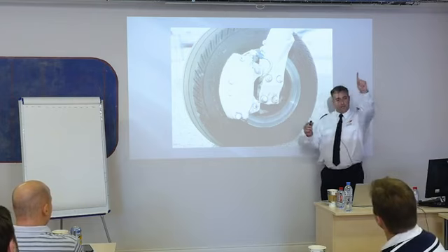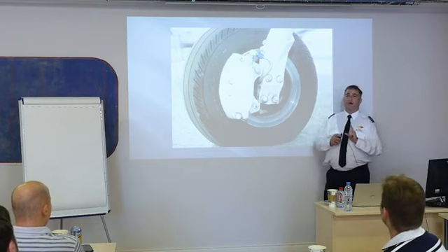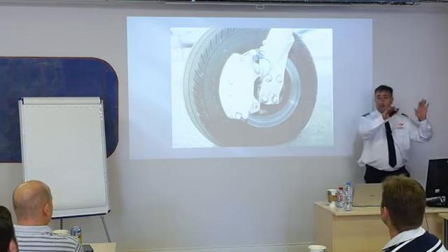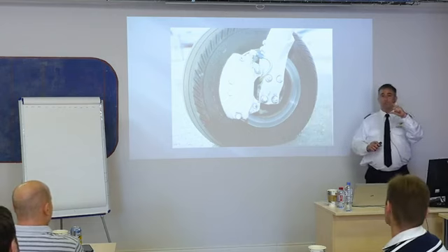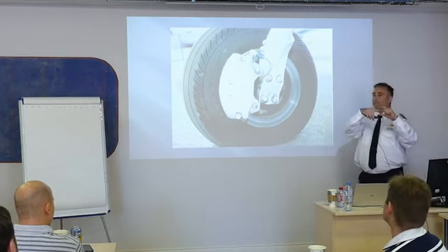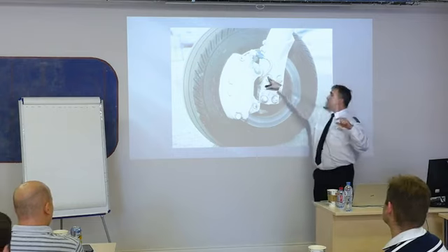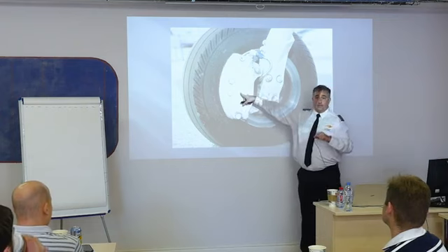This airplane has one hydraulic system, and it's very simple. There's a master cylinder behind each pedal, which is just a way of transmitting hydraulic pressure from your toe through this line to the brake caliper.